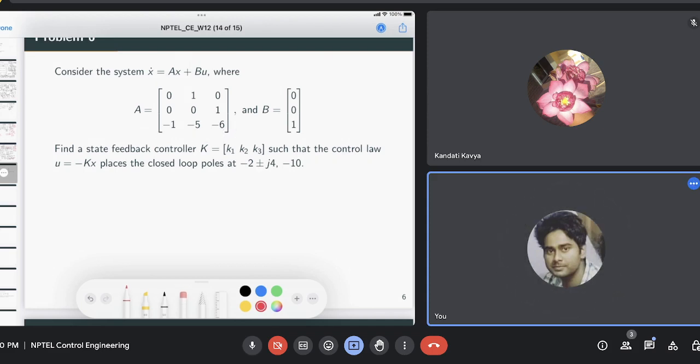Now you may have some desired steady state error, or you want some transient response, and that can always be translated into the pole location, right? So this is the desired pole location you want. Whatever you are given, this damping coefficient and this natural frequency, always translates into these dominant poles. Now the issue is that in the frequency domain you can just place this dominant pole, right? You cannot place this third pole arbitrarily.